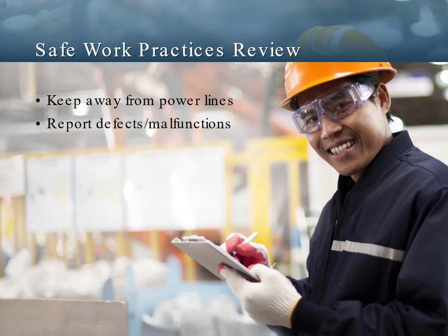Report any defects or equipment malfunctions immediately, and do not use the equipment until necessary repairs have been made by qualified maintenance personnel. Never alter or disable a safety device or interlock device, and be sure to check safety and interlock devices daily to ensure they are functioning properly.